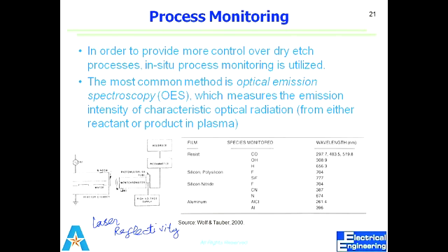So for photoresist, the species that can be monitored may be the hydrogen, hydroxyl group or carboxyl group. These have specific wavelengths, and we monitor that specific wavelength. The optical emission spectroscopy, that's why the name shows, you monitor the emitted wavelength, the intensity of this wavelength that is emitted. Initially the etchant should have high intensity because so much is available. After that, when they react with the surface, that should go down. So it means my etch process has started.